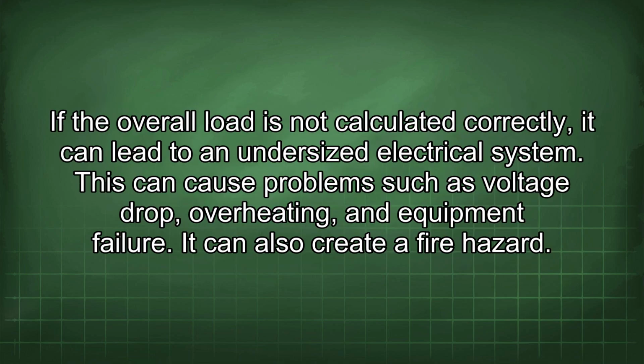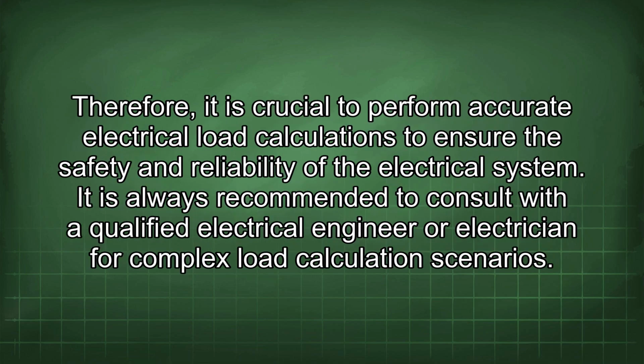If the overall load is not calculated correctly, it can lead to an undersized electrical system. This can cause problems such as voltage drop, overheating, and equipment failure. It can also create a fire hazard. Therefore, it is crucial to perform accurate electrical load calculations to ensure the safety and reliability of the electrical system.